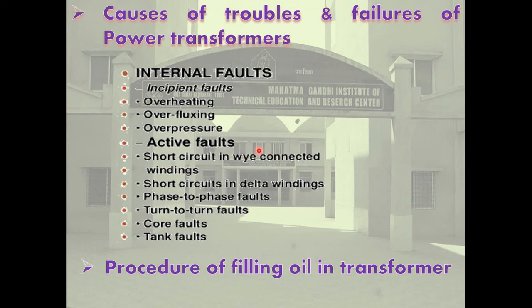External short circuit is caused by insufficiently cleaned overhead lines, accumulations of dust on insulation. Okay, so remedies: transformer windings should be capable of withstanding repeated external short circuits without failure, and overcurrent protection.